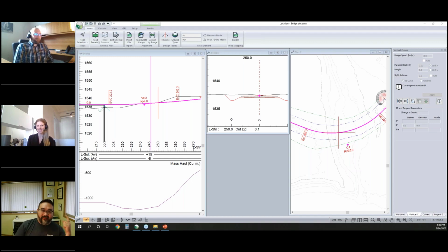So the one thing that I've been using lately more is where you export your designs directly out of RoadEng, and we carry around a little Trimble R1. It's a Bluetooth GPS unit that uses GLONASS and other things, so it can give you sub-meter accuracy. And we found in the timber, it actually gives even better accuracy than, say, an RTK. And with that, and having the actual plan view of the road, you can see exactly where you are on the road surface as you're walking around.